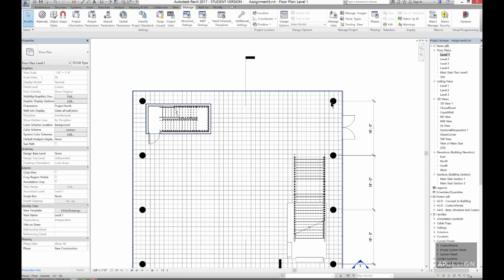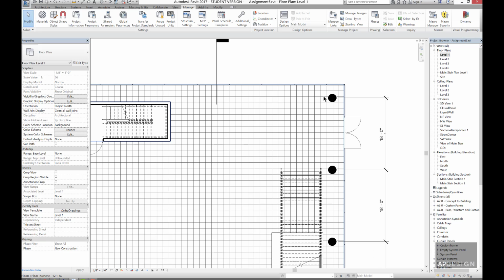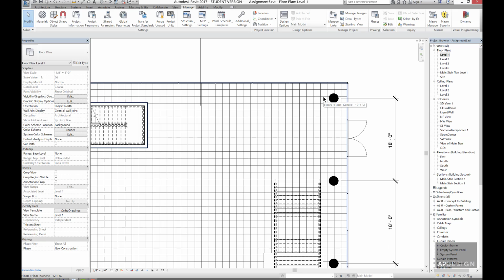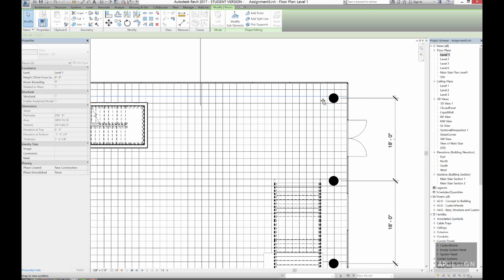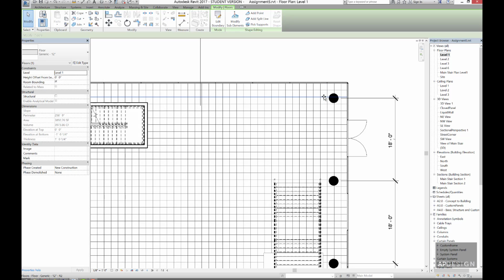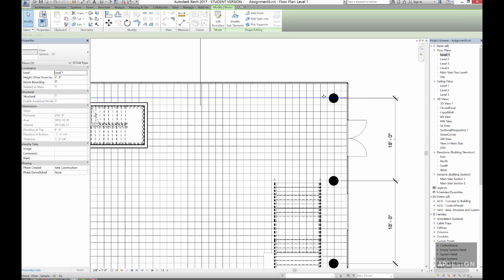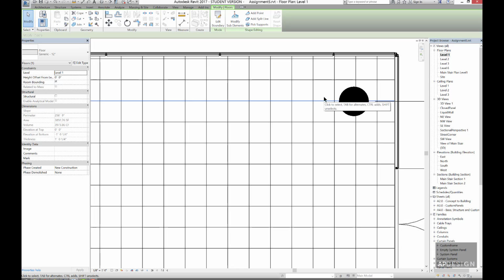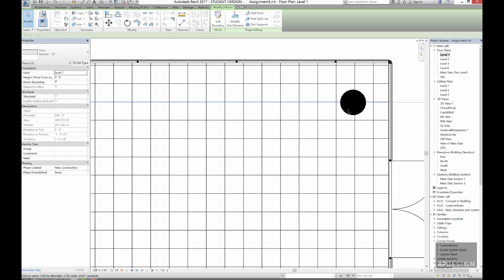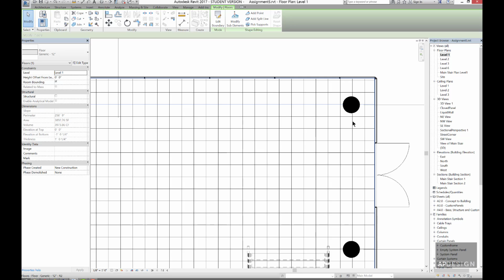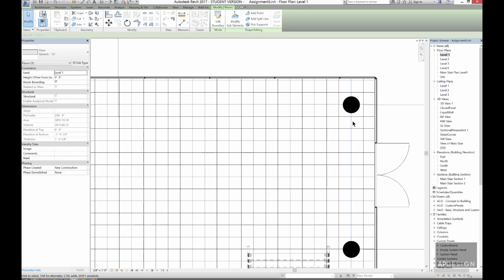Alright, so the pattern all starts at this top. It seems to be randomly placed left to right. So how do you move that? Well, it's really simple, but it's impossible to find unless you know this trick. You just tab over one of the lines that you want to move until it gets blue, and then you can move it. What we're looking for is to get it right there, maybe centered, and then you tab over for vertical and do the same thing.